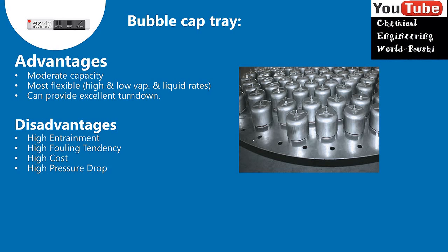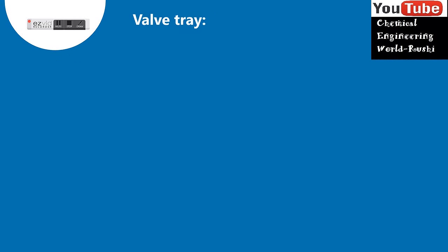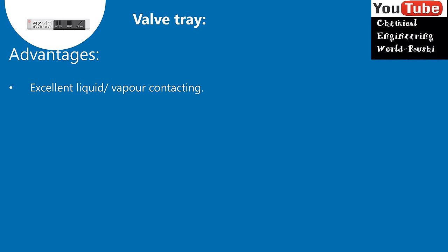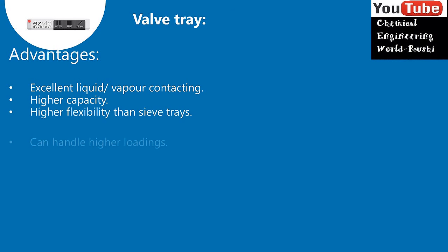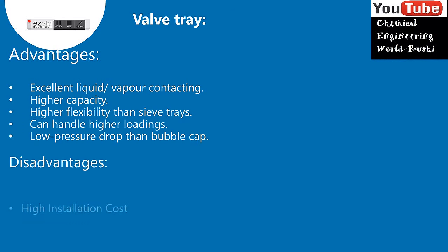Valve tray. A valve tray uses valves which rise as the vapor rate increases and then lower as the vapor rate falls. This stops the liquid from weeping. Valves can be round or rectangular, with or without caging structure. The valve disc rises as the vapor rate increases.